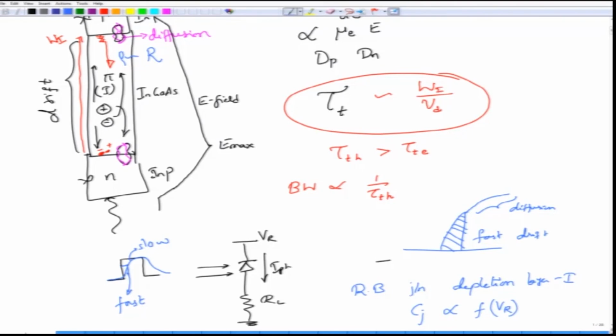Even if you make that part not depend on anything, your fundamental limit again comes from the transit time, which is again basically because of the capacitance, because the transit time is essentially how you are taking the semiconductor I region and then charging the I region, right. So, you cannot just bypass that capacitance that is sitting there. So, put all these things together, the response time of a photodiode is determined by all these characteristics.